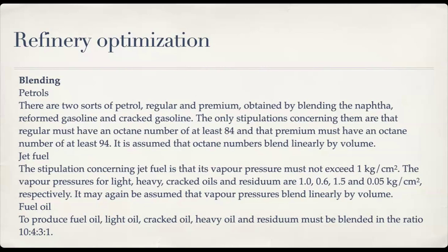What about fuel oil? For fuel oil, you must blend light oil, crack oil, heavy oil, and residue in a certain ratio, 10 to 4 to 3 to 1. So for jet fuel and fuel oil, you blend light oil, heavy oil, crack oil, and residue together, with different formulas.